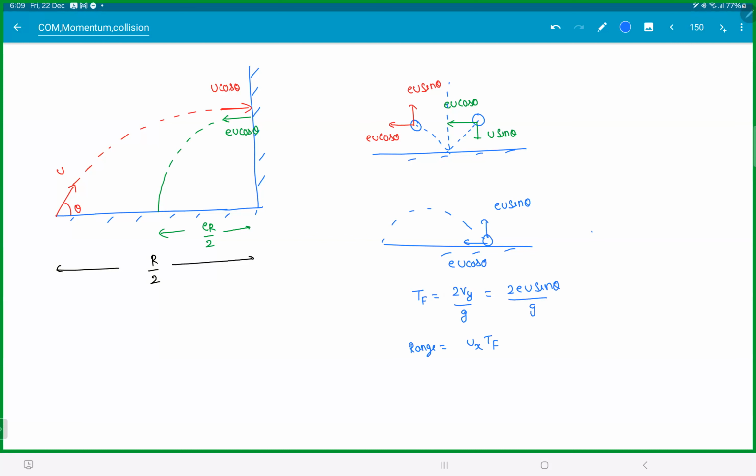That is definitely wrong. Look, do your dimensions match? That's what I keep telling you. When your answers have blunders, at least you should make a blunder that is sensible. You wrote 1 plus 16 u square by g. Okay, you wrote whatever it is. This thing has the dimensions of height. This is a dimensionless quantity. How do you add them? Got my point?